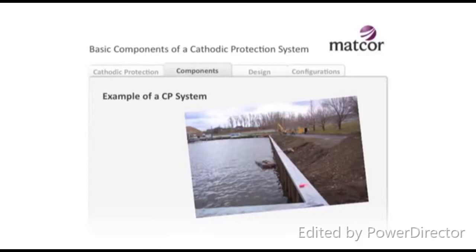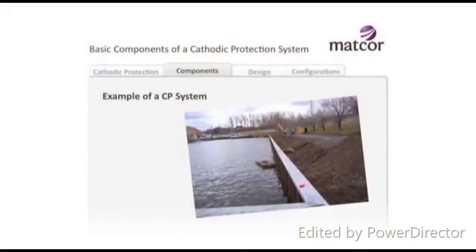Here what you see is very common in any type of near shore or on the shore facility. It's called a seawall. Basically they're taking sheet pile, which is metal sheets, and they pound them into the ground, and that separates the water from the land side. The nice thing about that is now you can dredge that area, and now you have an area you can bring boats up, and you can make that pretty deep even. So if you've got an LNG terminal where you're going to bring in large LNG tankers, you're not going to just run those up to the shore and have them hit the sand. You've got to create a deep channel where you can berth the LNG tanker. Seawalls are very common to do that.